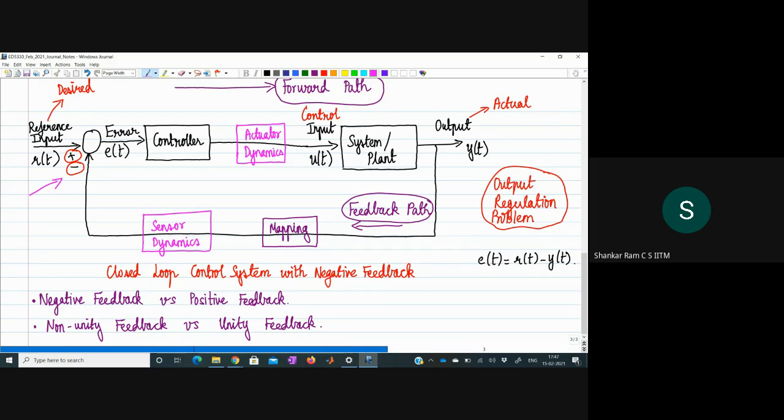You may have a rack and pinion mechanism in the vehicle for steering, which has to rotate the steered wheels in contact with the ground by another 2 degrees. If I have an electric power steering, then I need my electric motor providing that extra effort to rotate the steered wheels by another 2 degrees.